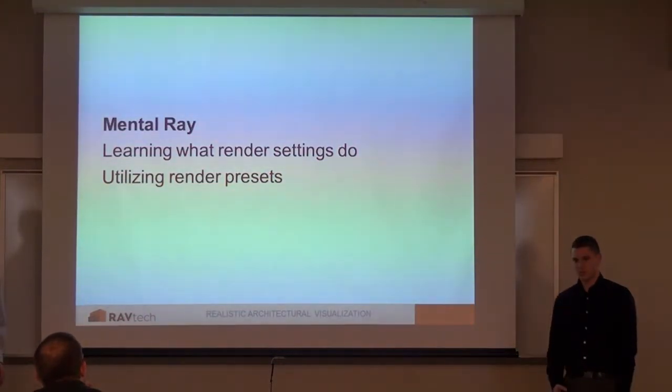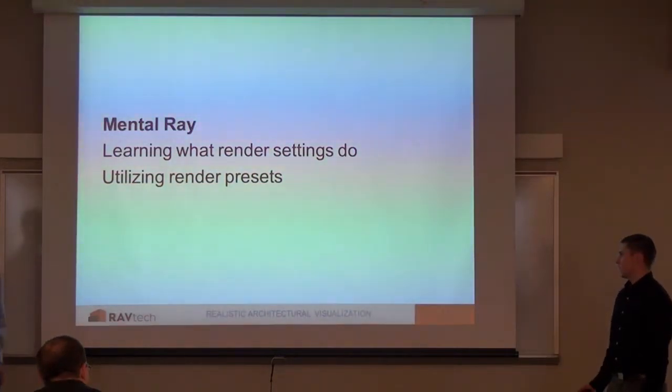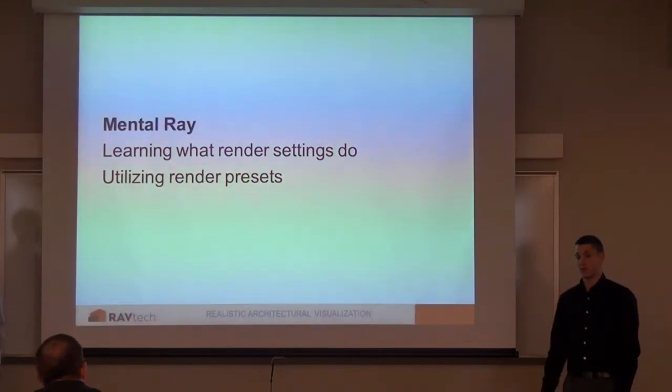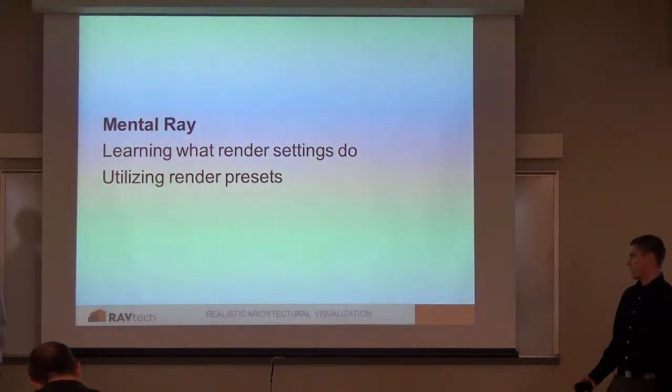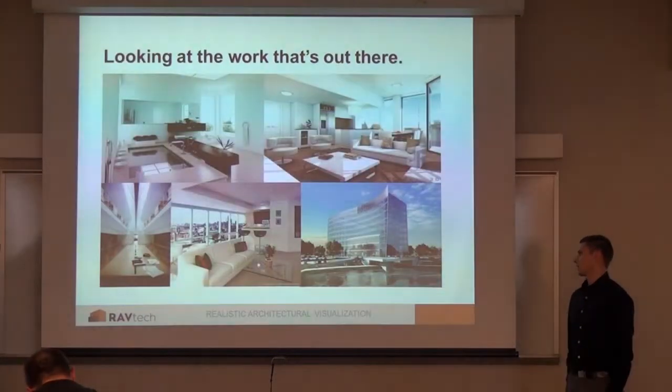Also looking at MentalRay, we decided to use MentalRay for this project because it was readily available to us. And we were learning what all the render settings do in MentalRay, how they affect your image, how they affect the render time, how they affect the quality of your image, and also using render presets, which we'll get into a little bit when we talk about our guidelines.